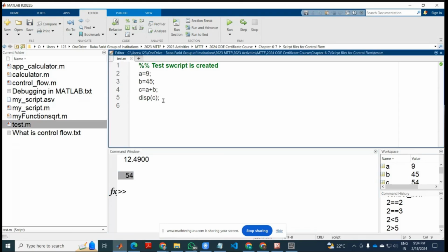If you want to divide into one more section, use this; this section is for multiplication. You can convert to different types of sections, or divide into slices this way by using the double percentage sign, and a single percentage sign is used for comments. Now this statement is a comment. If you use it, a new section has been created. When you want to run the code section-wise, your cursor must be in that particular section, and you need to press at this place.